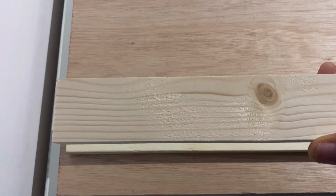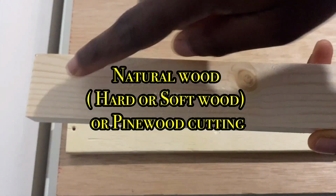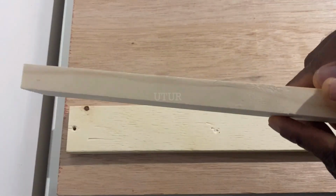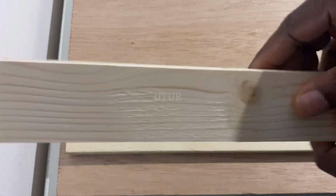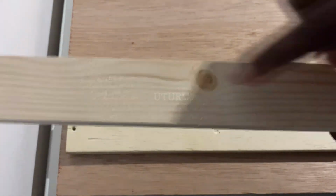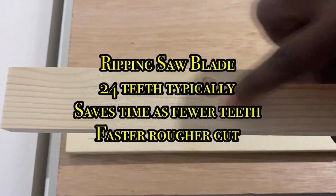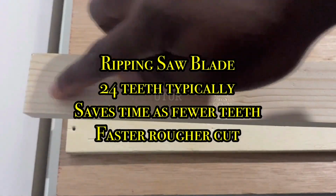For cutting natural wood, or in this case pine wood, we can clearly see that the grain structure isn't overlapping. It isn't random or chaotic along the grain of the wood and across the grain of the wood. And so you will need a dedicated ripping blade to cut along the grain of the wood.